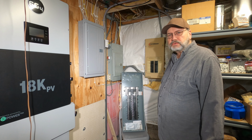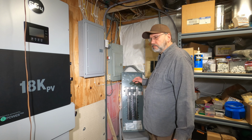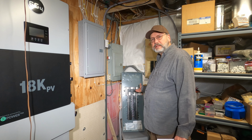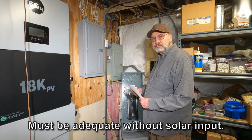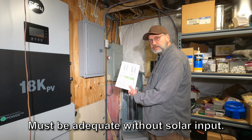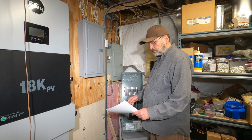Regardless if I add more solar or not, I need to know that I can install that 150 amp main breaker in here. And in order for this to pass inspection, the inspector is going to want to know if that 150 amp main is adequate and code compliant for this house. So if I do this load calculation, I'll be able to show the inspector that 150 amps is in fact more than adequate for this house, even without the solar input.